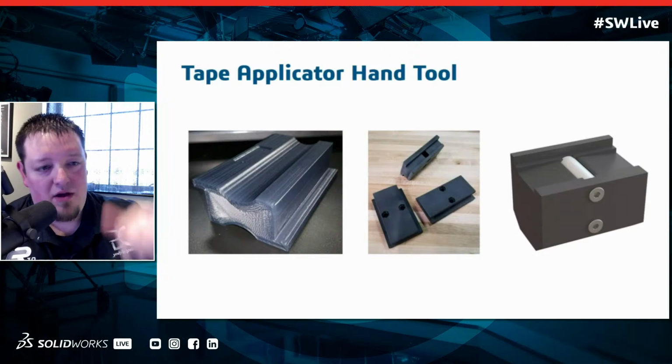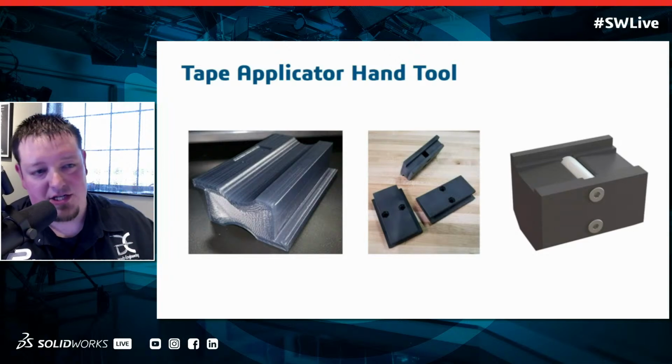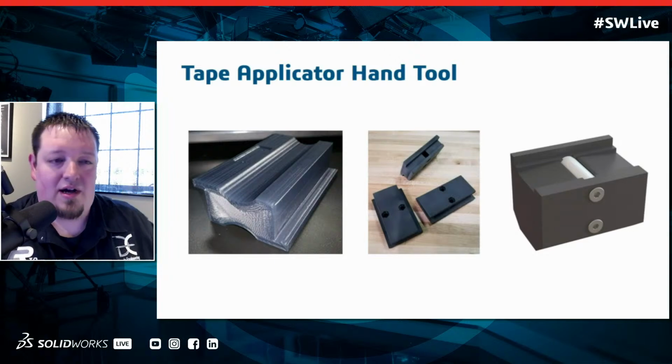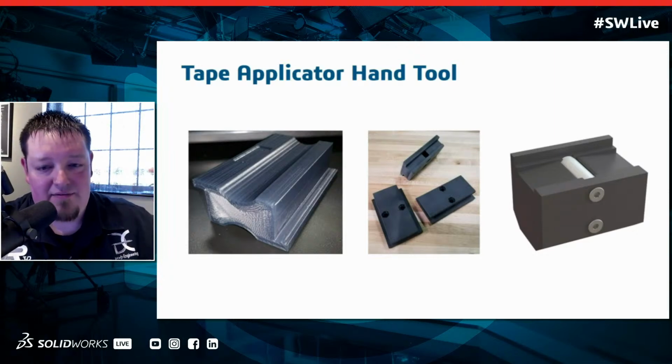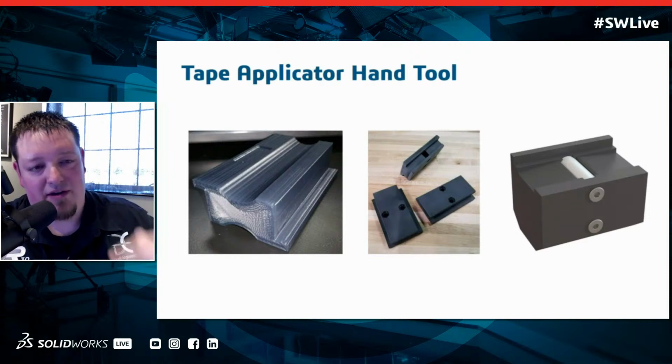So we literally print them, rip them off the print bed, throw them in a bag, ship them to the customer. It was the lowest cost option that we could come up with, but it was important for us to design it for additive because we could eliminate so much secondary work from having to deal with supports.